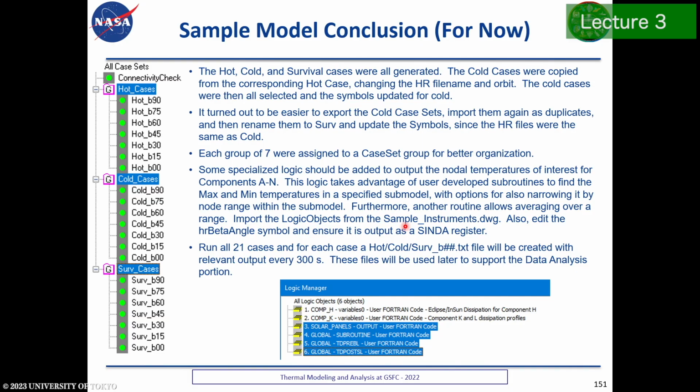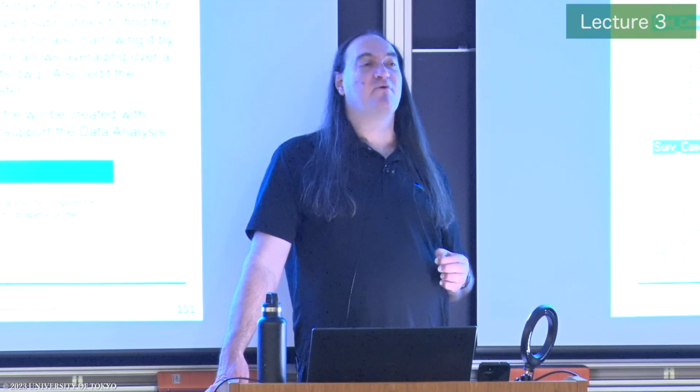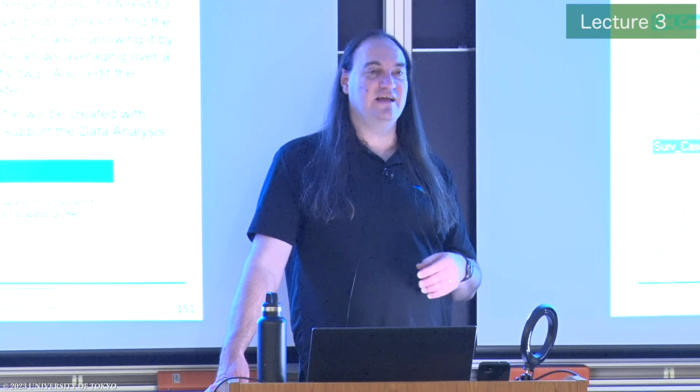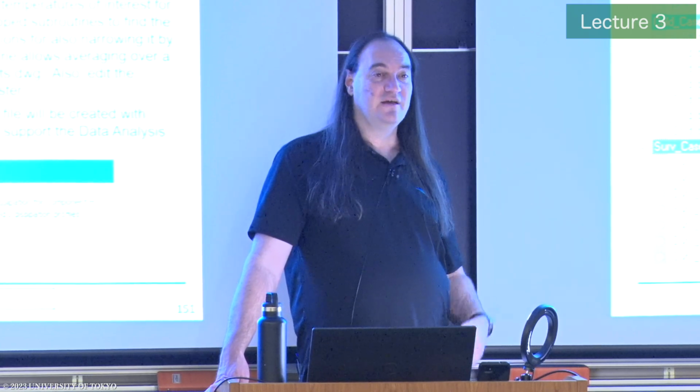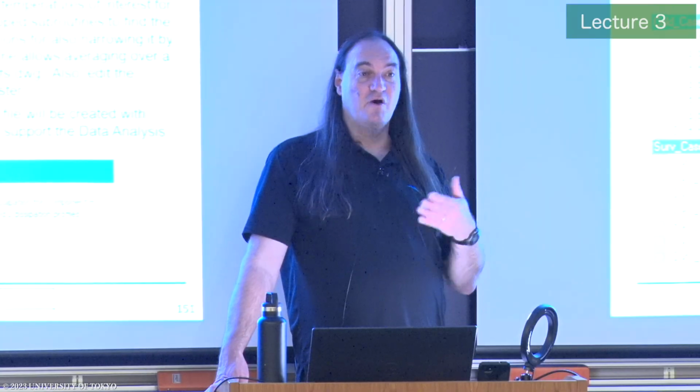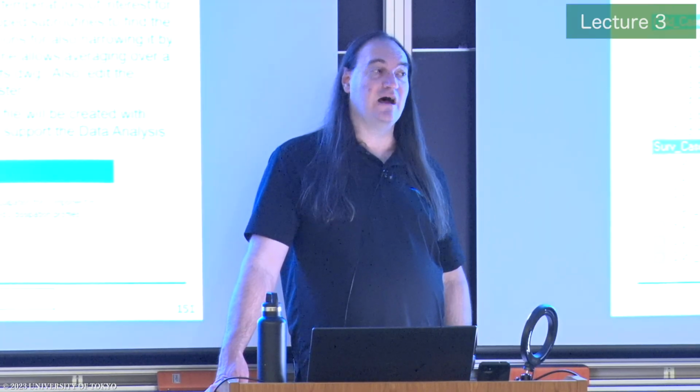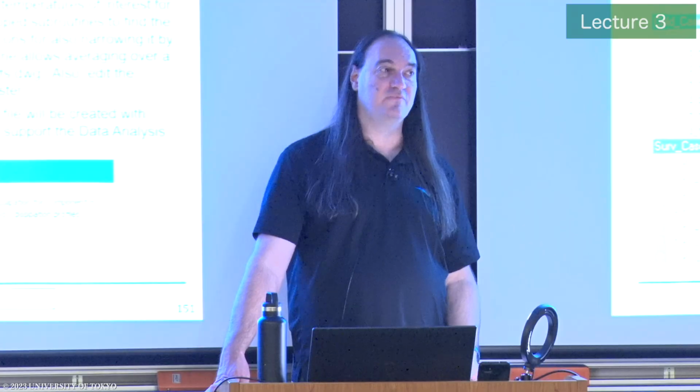So I am very much a fan of bringing my data into Excel and manipulating it there, which is one of the reasons that I'm an advocate of numbering things in a way that I recognize what it is, rather than just auto-number everything and let the contour plots do what they want. If I know that node 1000 is the motor, then I can use that knowledge when I'm extracting data from the full set.